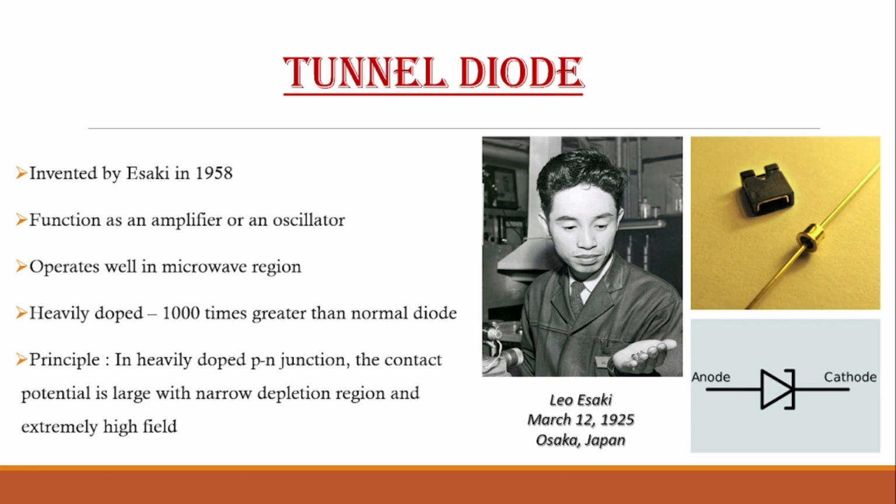So in this we can understand the construction of tunnel diode, that is, it is a highly doped semiconductor material, and the materials typically constitute an N-type semiconductor and a P-type semiconductor. The main point is the doping levels are maintained at an exceptionally high degree to establish a narrow depletion region, and this is going to contribute to the tunneling.